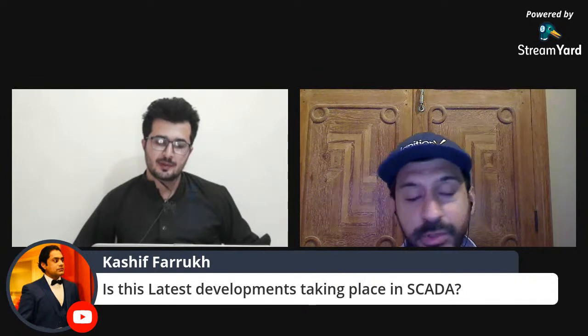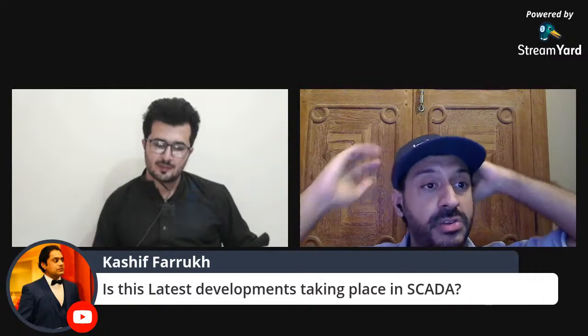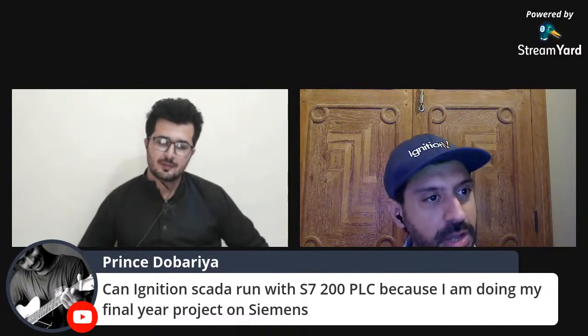What are the latest developments taking place in SCADA? I would say machine learning and AI integration using IIoT. SCADA software is adapting to enable communication using the MQTT protocol. OPC UA is not what it used to be. OPC UA was the primary option of communication. Now it's changing, and MQTT is creeping its way into the SCADA industry.